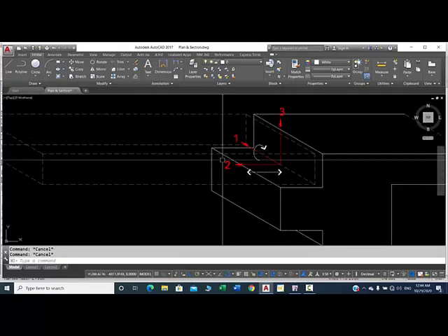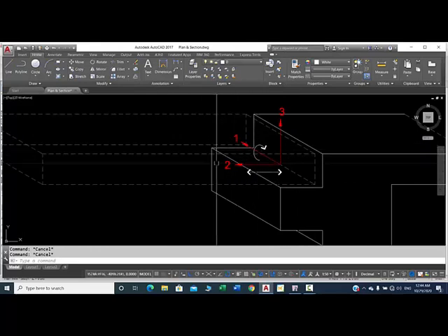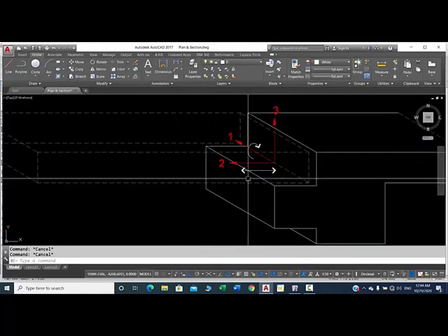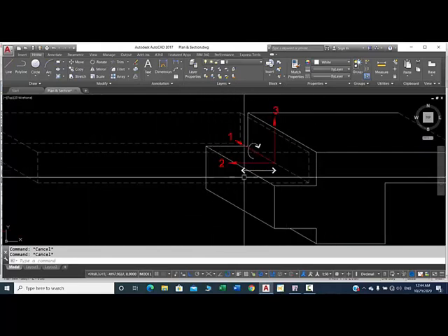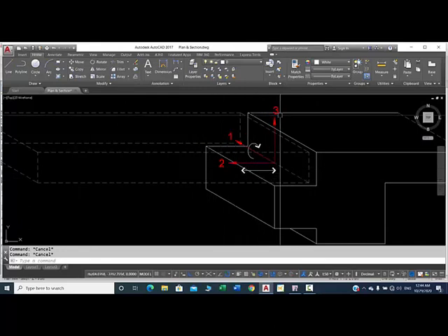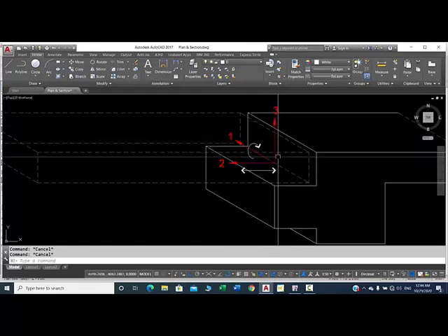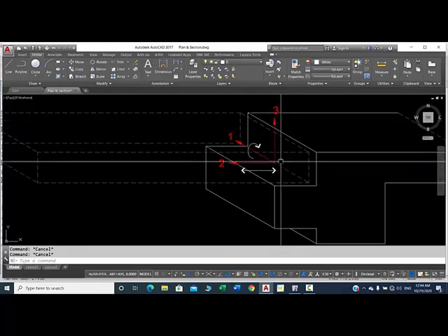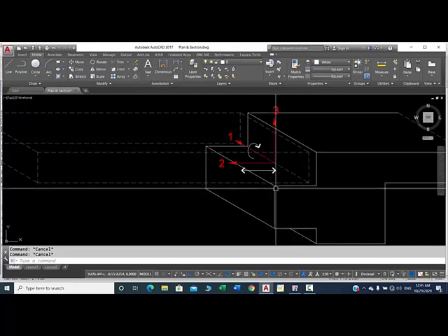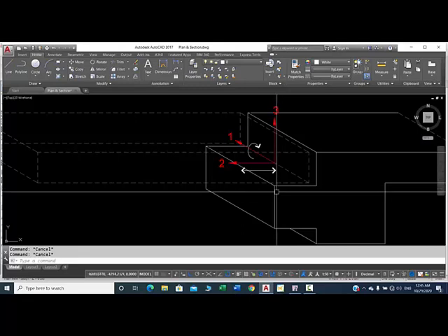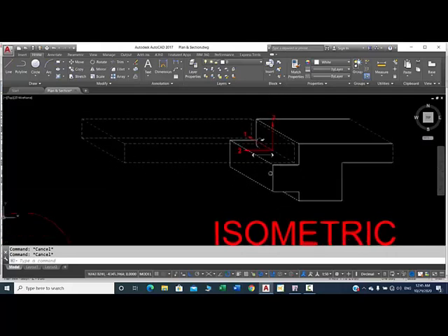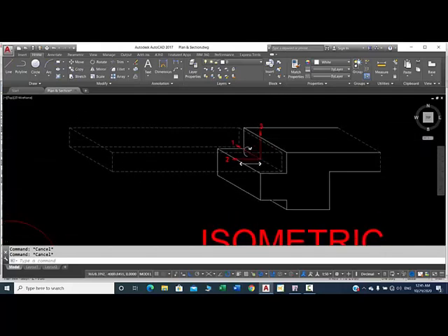So we have to release the slab rotation along axis 1, and also the axial or the shear along axis 2. But on the vertical, we don't need to release the shear capacity of the slab, because we have a ledger below it, so it has the capacity to resist the vertical load. So we don't need to release on that local axis.